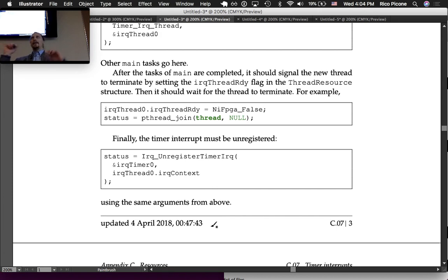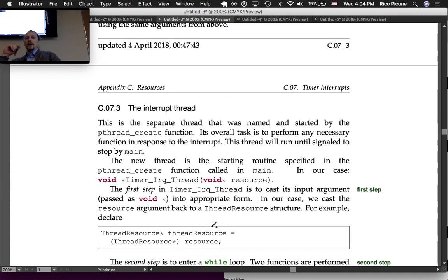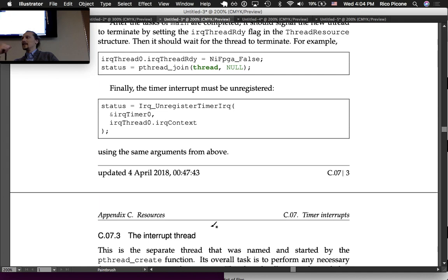So this is giving you the beginning and the end of your main, and you have to put a little bit in between, just like before. The main stuff is kind of bookkeeping, administrative stuff in main. And remember what we're doing in main besides setting everything up is we're waiting for that backspace character. When you see that backspace character, then you have to terminate the IRQ thread.